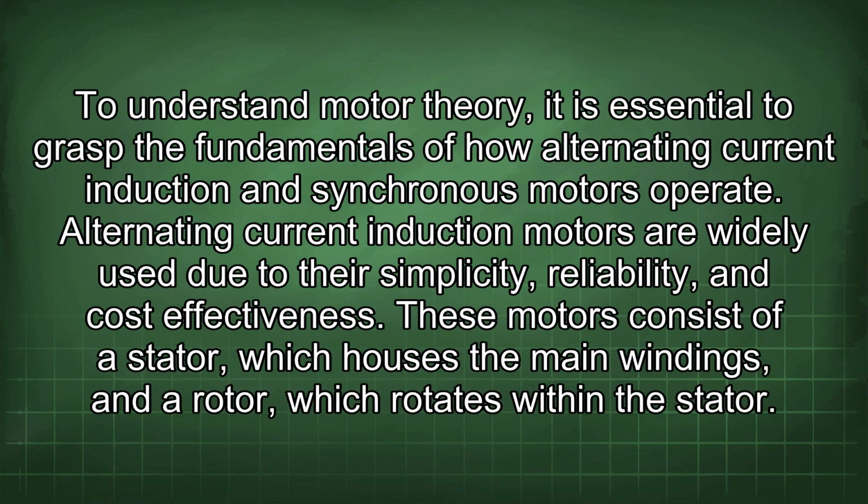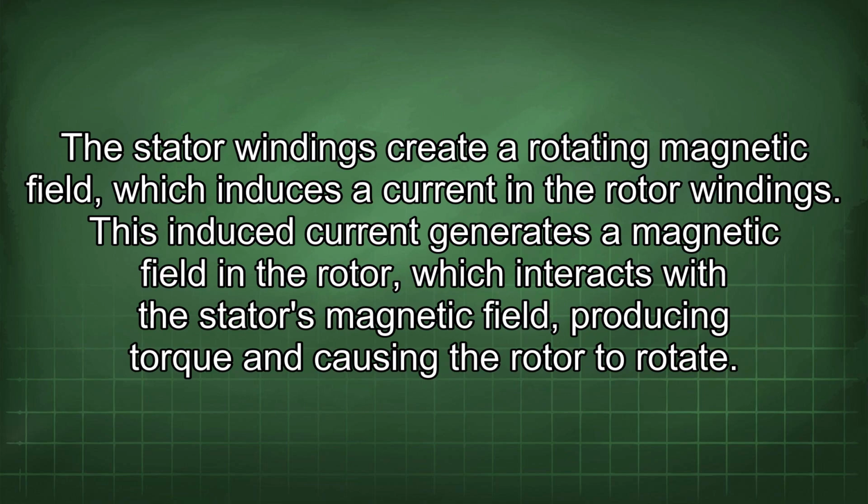To understand motor theory, it is essential to grasp the fundamentals of how alternating current induction and synchronous motors operate. Alternating current induction motors are widely used due to their simplicity, reliability, and cost-effectiveness. These motors consist of a stator, which houses the main windings, and a rotor, which rotates within the stator. The stator windings create a rotating magnetic field, which induces a current in the rotor windings. This induced current generates a magnetic field in the rotor, which interacts with the stator's magnetic field, producing torque and causing the rotor to rotate.